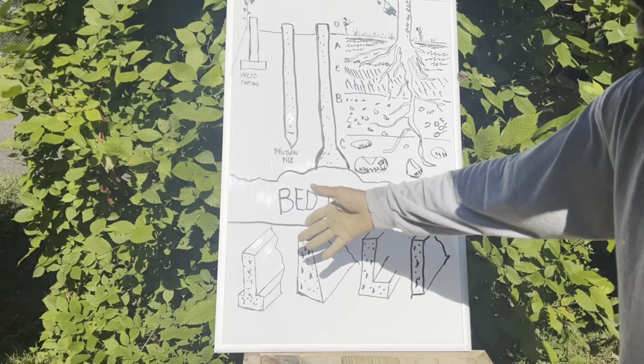Because if you got the wrong foundation in your soil, it can settle unevenly, and that's what's going to cause the whole structure to start to buckle. You're going to be getting large cracks, and then your joists, your rafters and everything is going to start to twist, and you're going to have a lot of problems when your structure starts to settle unevenly.